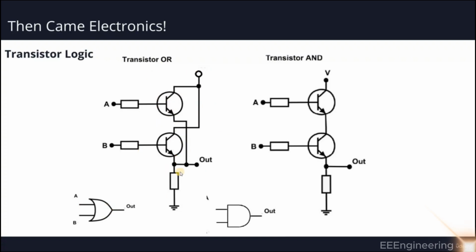Electronics or transistors are connected with each other in this form right here. Same thing at the end. Whenever you see this symbol, this is an AND gate, which is the same as two switches in series together. If you go inside it and take a look, you're going to get a topology that looks like this or similar to this. So this is a black box encapsulating this type of logic for the OR and here for the AND.